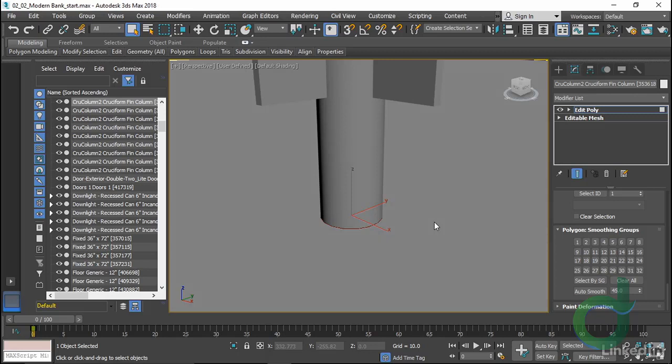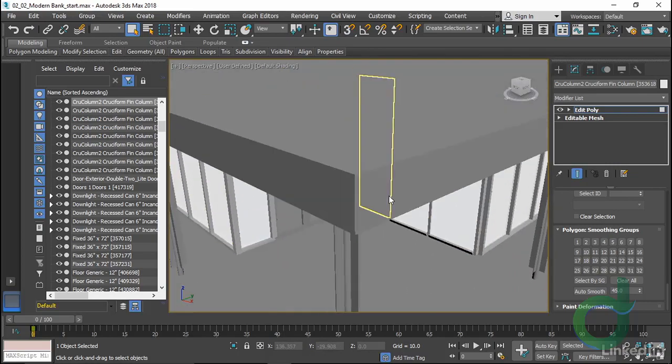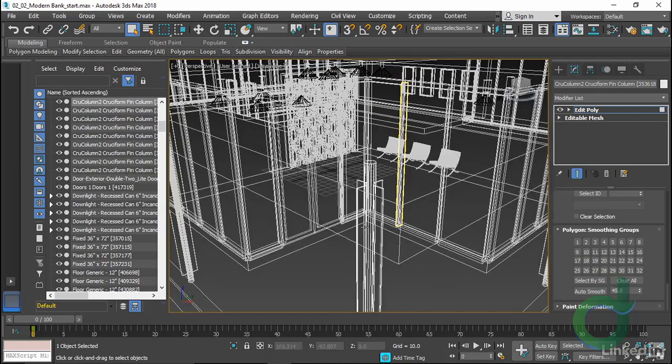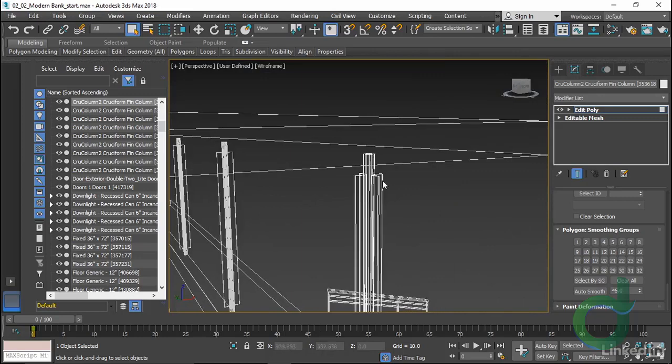This is an extra poly I'm not going to need, as it's facing exactly down to the floor. We can see it's there, both by the tiny bit of red highlighting the selection and the transform. I'll press Delete, and now it's exactly gone. I'll press F3 to go to wireframe, orbit around, and do the same at the top.